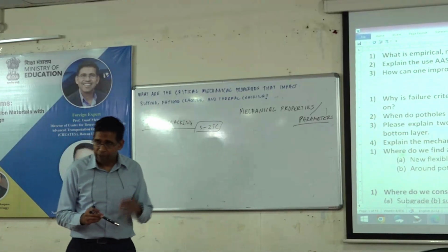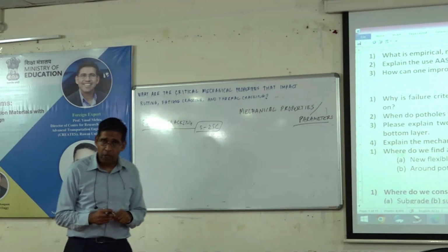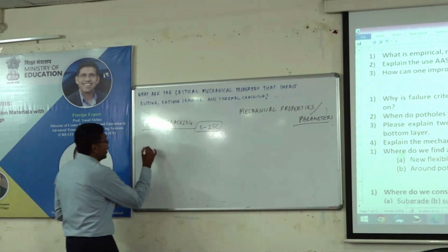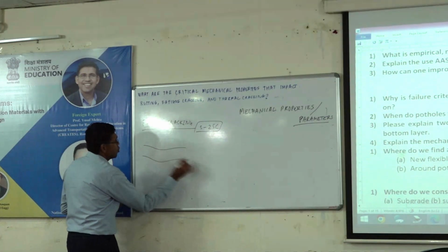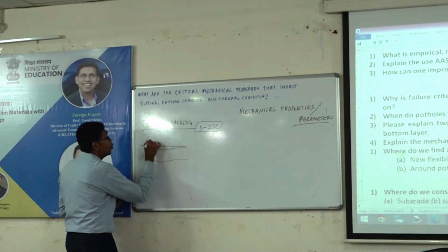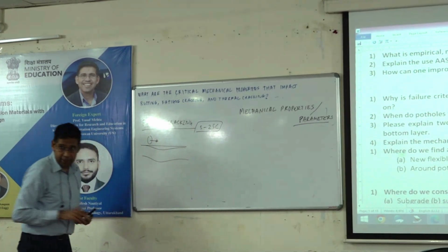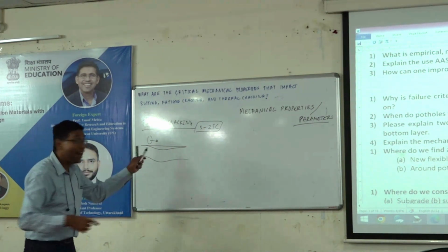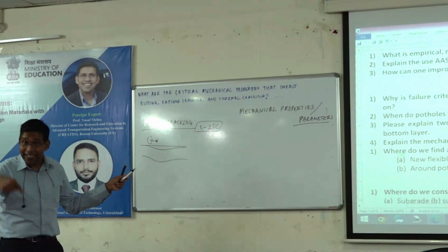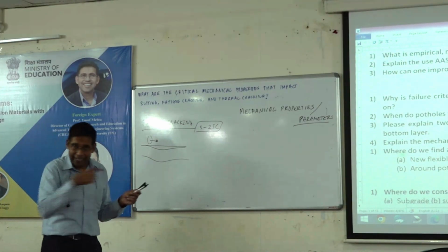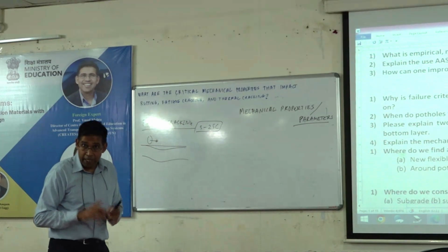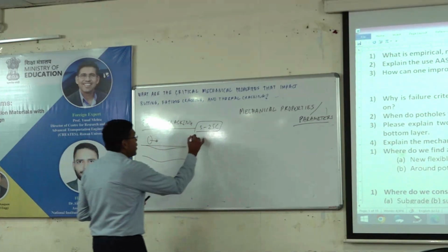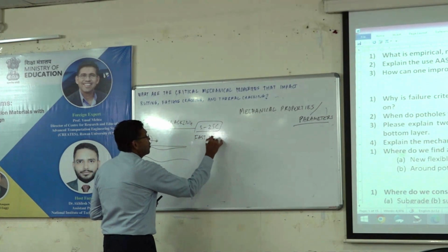How does it happen? First, try to understand how it happens. Repetition of load. Repeated load. Repeated loading, correct? So you have repeated loading, it happens during fast moving traffic, right? Somebody mentioned increase the speed of traffic. Now this happens during heavy, fast moving traffic. So if I increase the traffic, I will create this problem, right? There's always a risk in doing such a thing. This happens mostly on highways, with fast moving traffic, right?